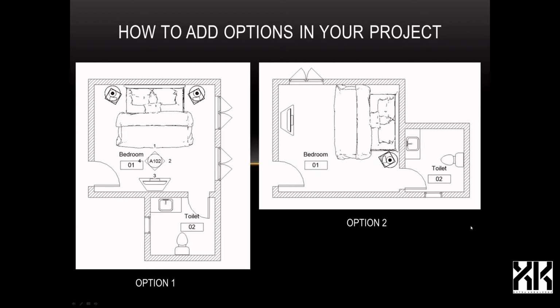Why do we need to make our options in the same Revit file or project? Can it be in two separate files? The answer is yes, it can be, but not advisable, and the idea is not professional. Imagine that you are working in two separate files and doing other work or modification in a common area. Your common work in one file will not automatically update in the other. You need to duplicate or redo it manually. How tedious, isn't it?